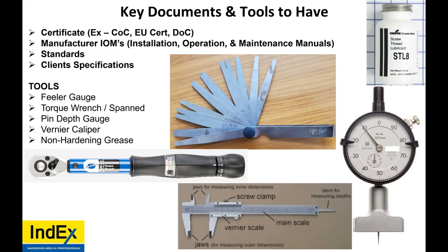How to determine the power rating of an EXD enclosure? Does the EPC need to populate the power rating? No. For EXD, if you're talking about flameproof, it is tested and certified. The manufacturer puts their equipment in it and it gets sent to an IECEx approved or ATEX testing laboratory and certifying body. For explosion proof, they don't worry about the temperature so much, but you can have it done. Or if you just have terminals, you don't need to do anything. You can sometimes put whatever you want into it.